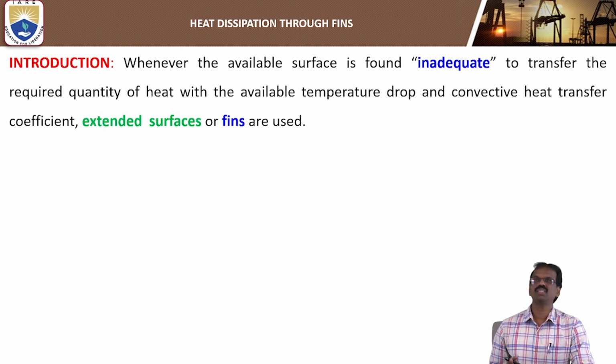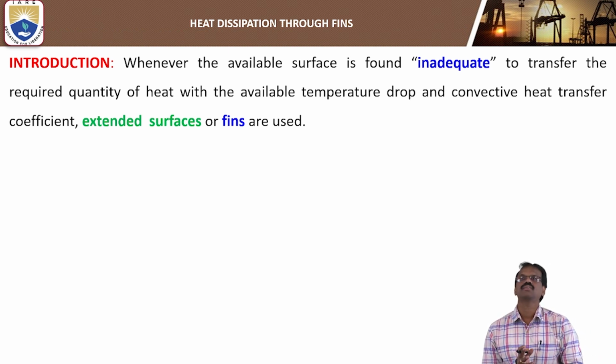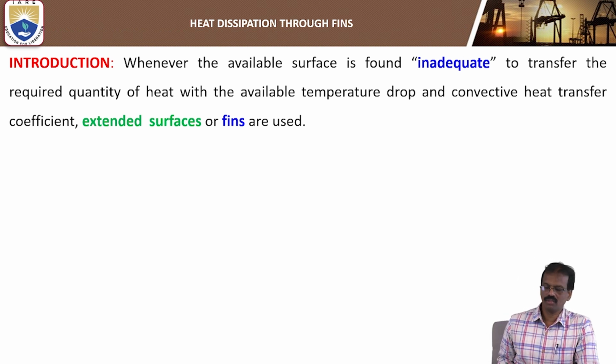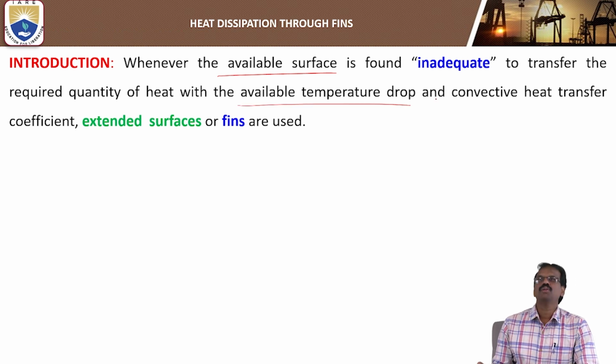First of all, we'll see what is the importance of fins and what is the general heat transfer equation for the rectangular fin, particularly the long fin. Whenever the available surface is found inadequate to transfer the required quantity of heat with the available temperature drop and convection heat transfer coefficient, we add extended surfaces.